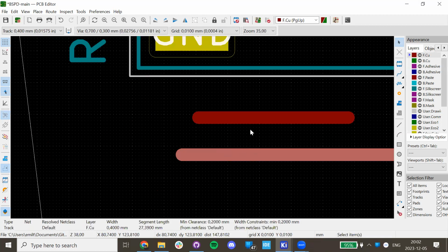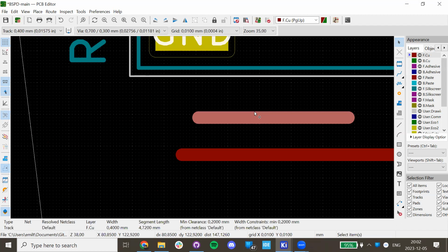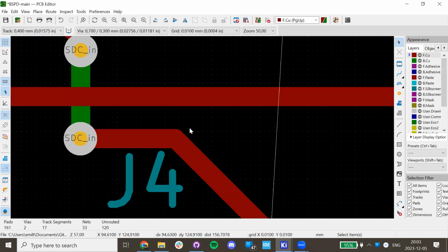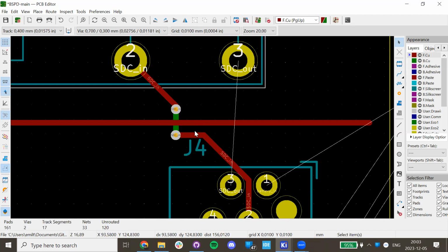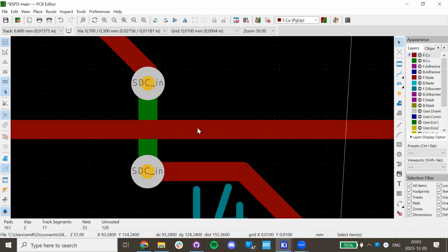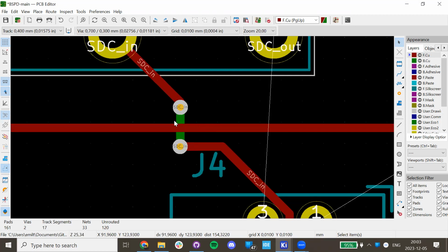This is what a capacitor is. It's like 2 metal planes with something in between them with different charge. So there will be a capacitive coupling between everything that you route that is close to each other. So here these two will have some capacitance in between them. Of course, this is very, very small, but the more sensitive signals you start to work with, I mean, the more important these things gets. So the habit of trying to keep perpendicular traces like this is very, very good.